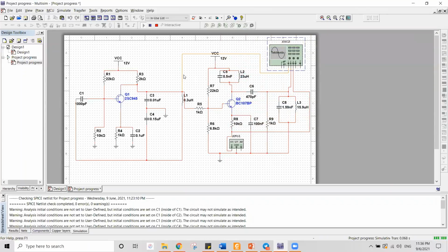Okay, so the AM modulator circuit is right here. Modulating is a process to combine or add two signals, which are the information signal and the carrier signal. The amplitude will change. The modulator adds the carrier signal and the modulating signal and comes out with a modulated signal as an output. We will see DSBFC, which is double sideband full carrier, amplitude modulation with carrier.